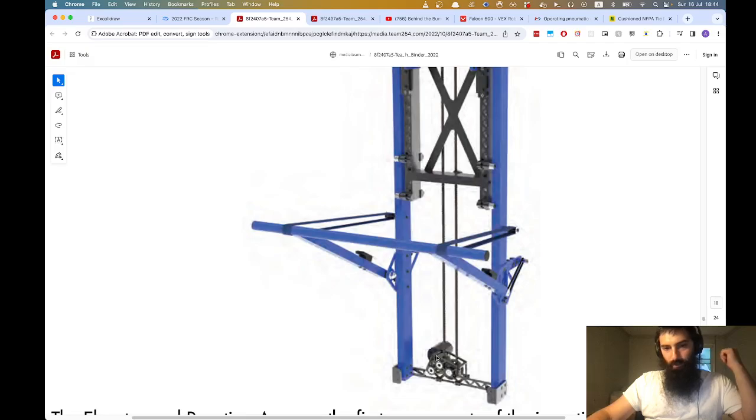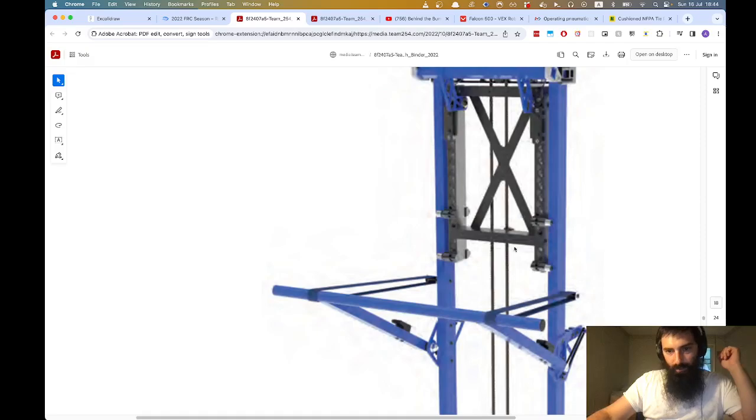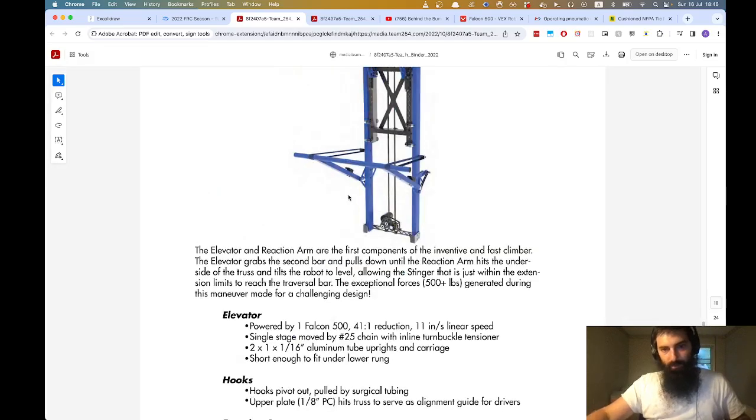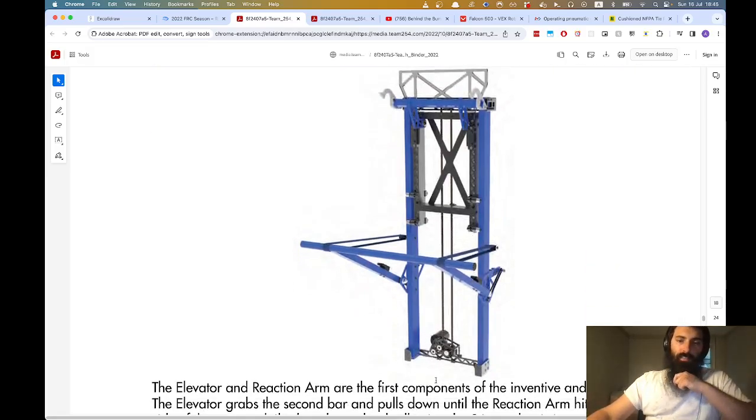So what happens is when the motor moves, this chain moves either clockwise or counterclockwise. And you can see how this motor actuates this carriage, which is right over here. I believe at this point the chain is fixed to this carriage. So as this chain moves up, this carriage also moves up, and as the chain goes down, the carriage goes down. So that's in essence how an elevator works. So there's a single motor.